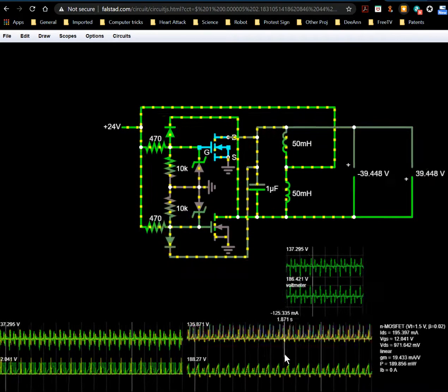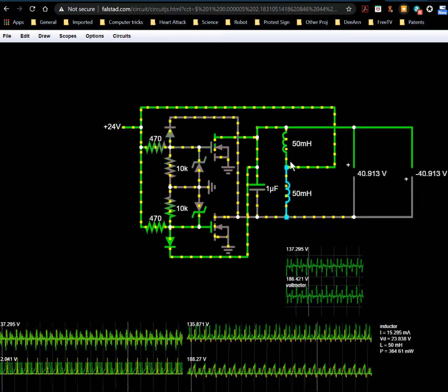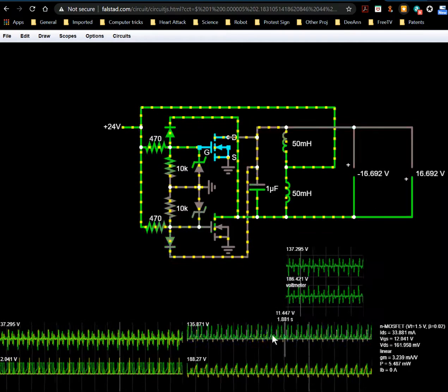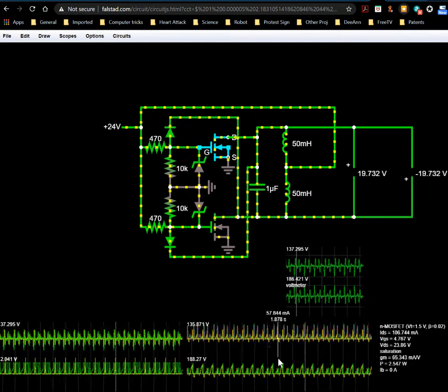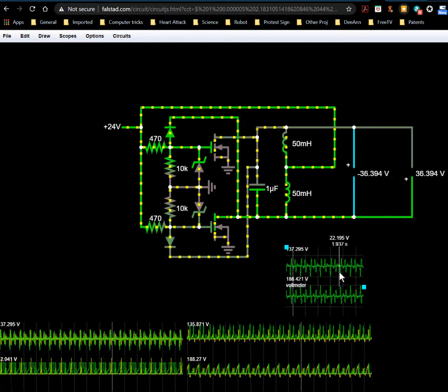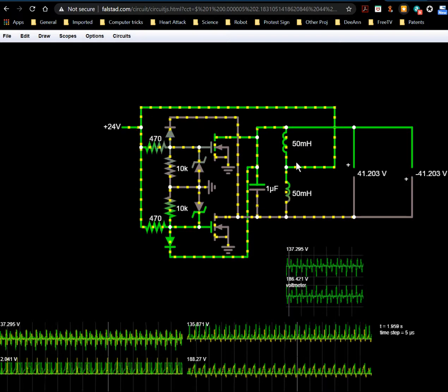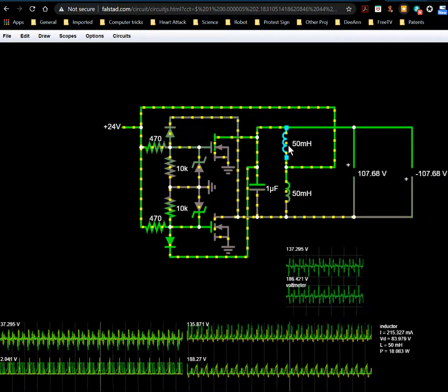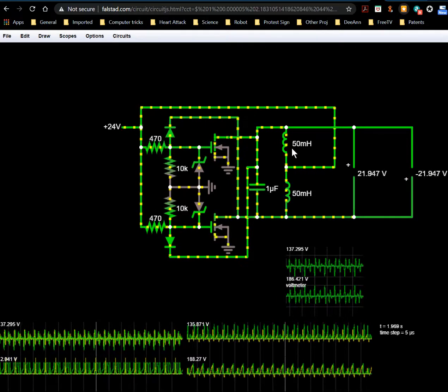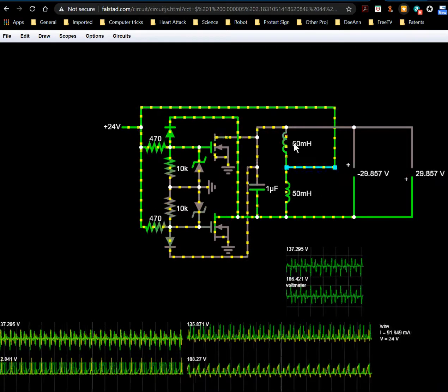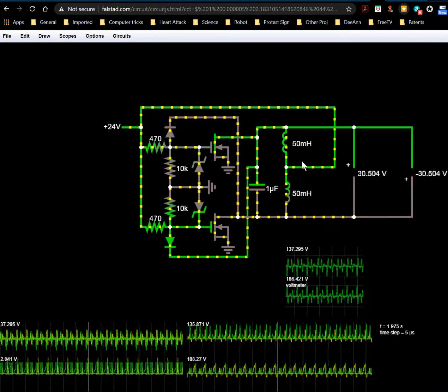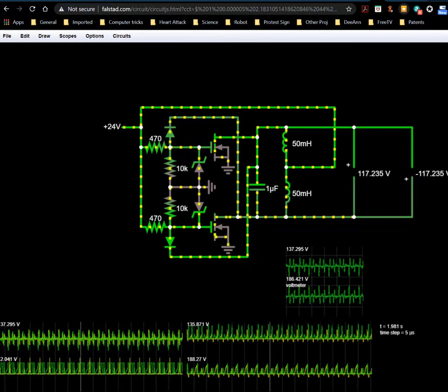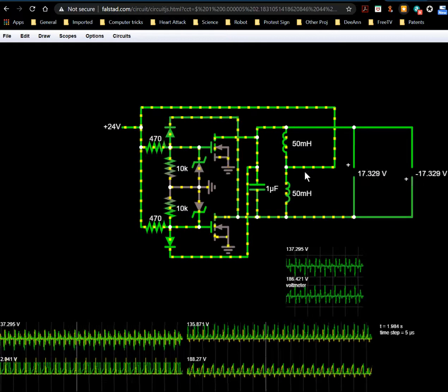You'll get this if you model this as two separate inductors that aren't coupled. So it looks like an electrocardiogram or something. I don't know if this would be the case in the real world, but it probably would be something freaky, because these really should be connected. They should be not just in series electrically, but actually magnetically coupled too, so that they operate as a proper tank oscillator, which is really a Hartley oscillator.